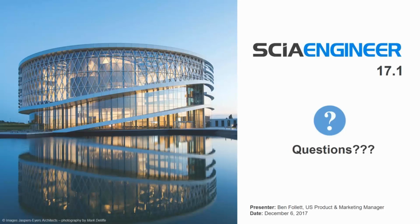So the first question was, is the punching check undertaken on transfer columns loading the slab from above? Yes, that is taken into account automatically, and you have the possibility to see that value graphically. Somebody asked about the single check functionality for punching. That's not yet supported. However, the new solution will take that possibility into account, and everything will become automatic to save time. So really it's just kind of rolled into there.